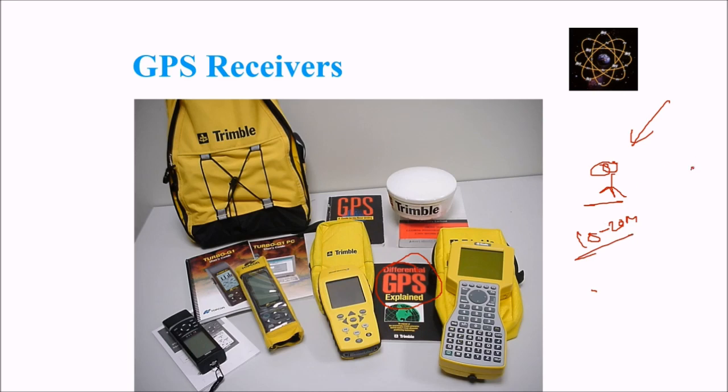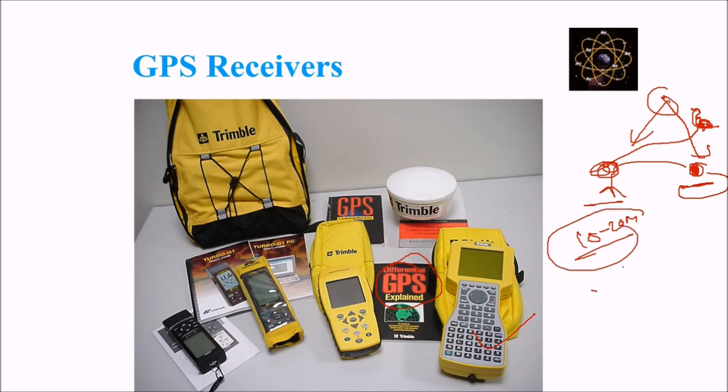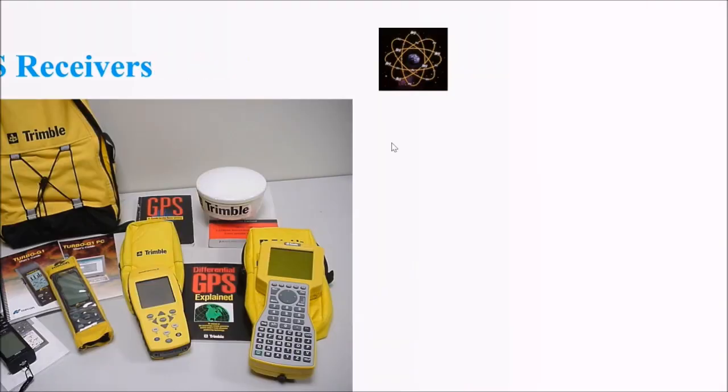So what happens here is that there is a ground segment, whose location is exactly known, and which you can interact with. It knows its location. So when it receives the data from the satellite, say it is getting position X, and it knows its position is Y, the difference is Y minus X. It knows that this Y minus X is the error which the satellite is right now generating, and this difference is sent to the individual receiver, and that is adjusted, and then you can get sub-centimeter level accuracy. This is the power of GPS and differential GPS.